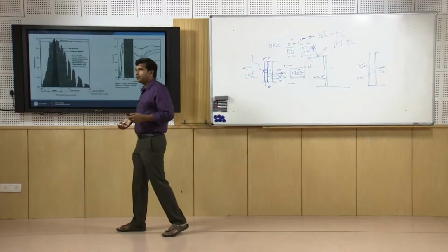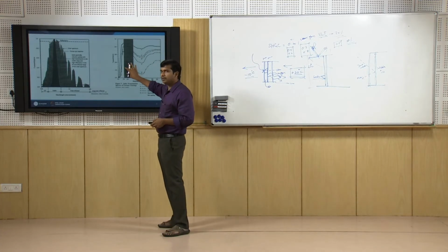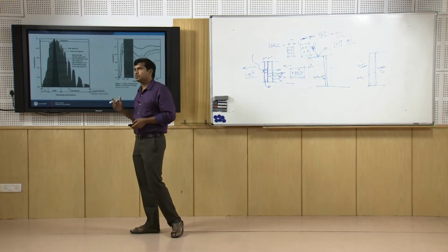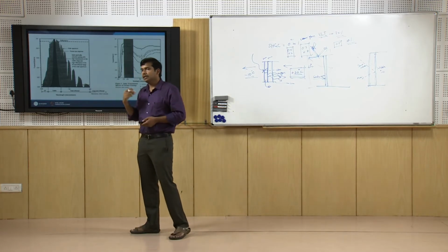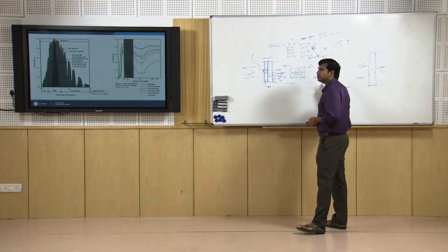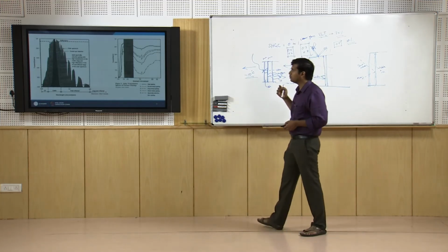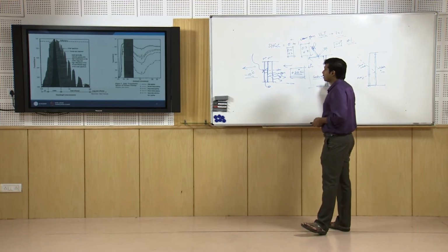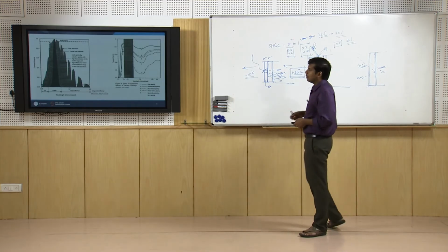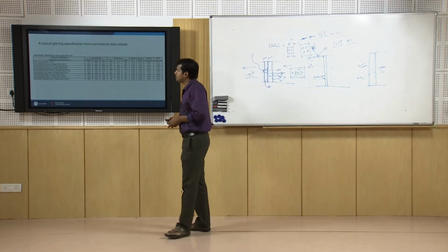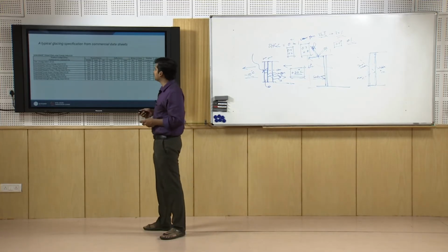But one thing we need to note, with the effect of coating it is possible, but apart from this, the use of a shading system also, by cutting down the source itself, that is direct incidence, is also very effective. If you are willing to go for a shading system, it is much more effective and economic than providing improved efficiency for the glazing system. I have referred to one of the commercially available catalogs, this corresponds to one company.